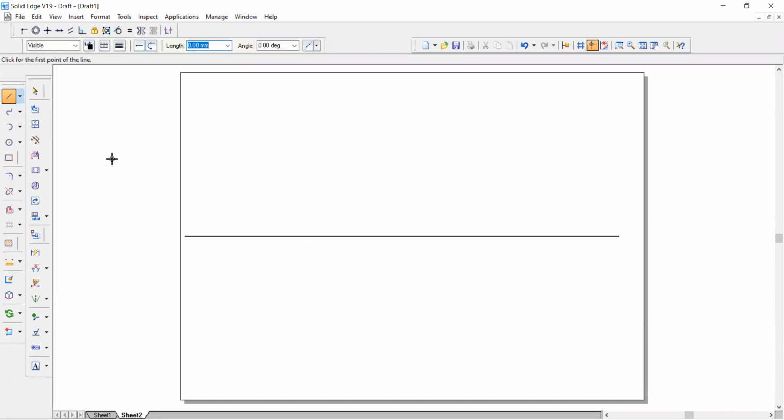So I am taking one problem on pentagons, which is resting on slant edges. He will just say slant edges, not triangular, slant edges. Before we start this, you must remember that slant edges means it will always rest on your corner. This particular problem number is 36. You can go through that. Slant edges means you have to draw it in corner condition.